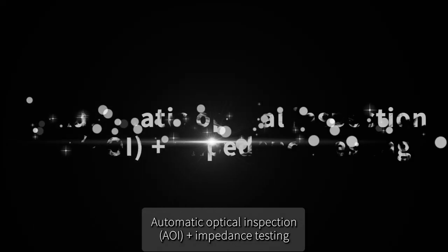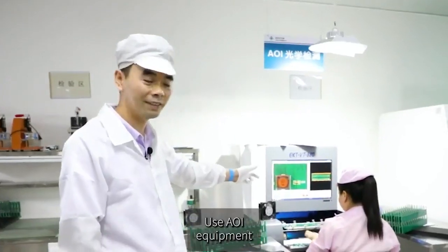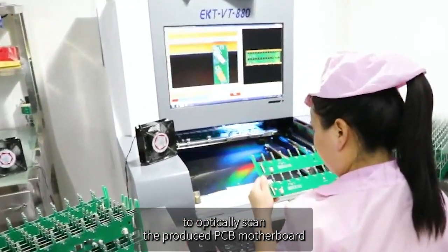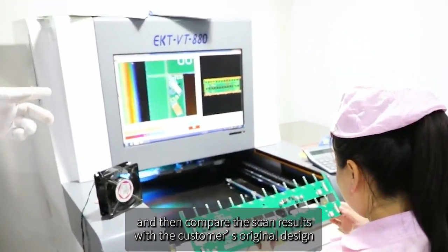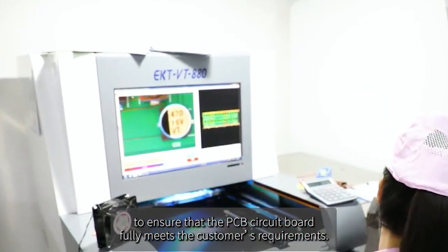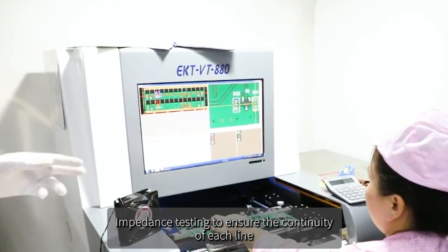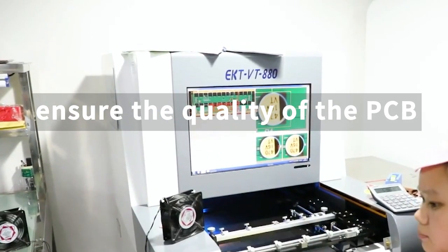Automatic optical inspection (AOI) plus impedance testing. Use AOI equipment to optically scan the produced PCB motherboard, and then compare the scan results with the customer's original design to ensure that the PCB circuit board fully meets the customer's requirements. Impedance testing to ensure the continuity of each line, to further ensure the quality of the PCB.